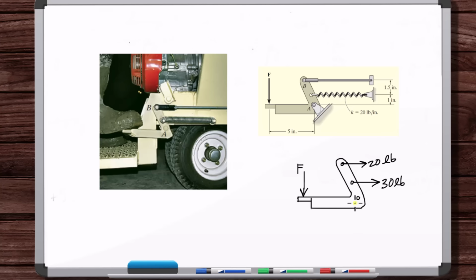So if this is the X and Y axis, you could put an unknown force, we'll call it A because it's at point A, in an unknown direction. And with unknown forces, just put any arbitrary direction because the final answer is going to tell you the sense. Or what's more commonly done is you do it this way. Instead of specifying a force magnitude and an angle, you just put an Ay and an Ax, and you just put them in the positive directions, right?